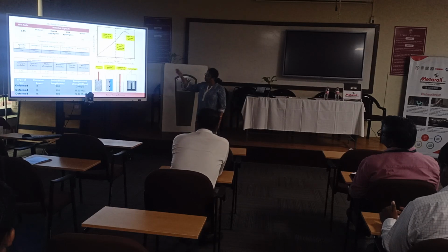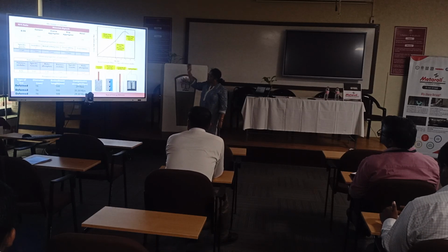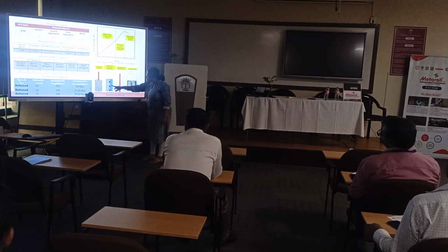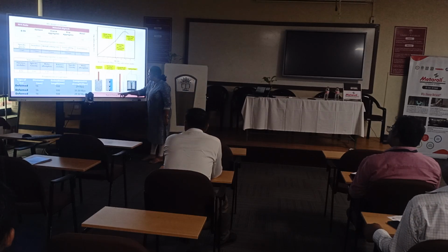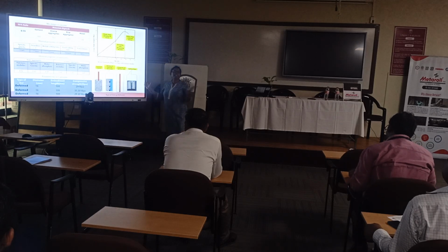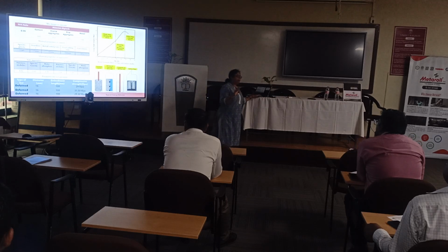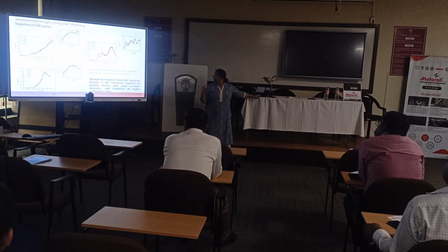So how does it happen? You have a specimen under a pull-out action, then there is crushing of the surrounding concrete, then the crack radially propagates and the overlying concrete splits into halves. This is the very common pattern that we see in our tests.